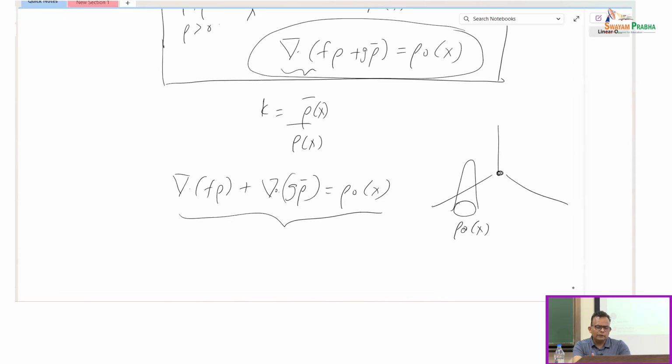Now, if you design this feedback controller so that everything eventually gets to the origin, all this mass is basically getting transported to the origin. When this mass moves, it passes through different regions in the state space before eventually getting to the equilibrium point.